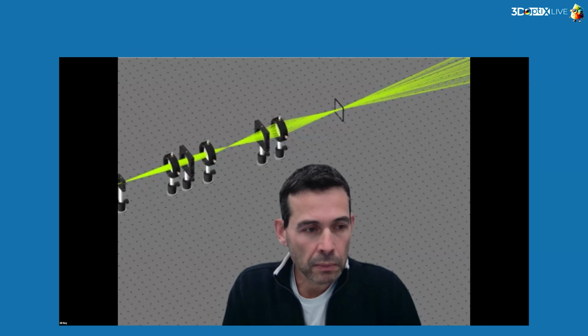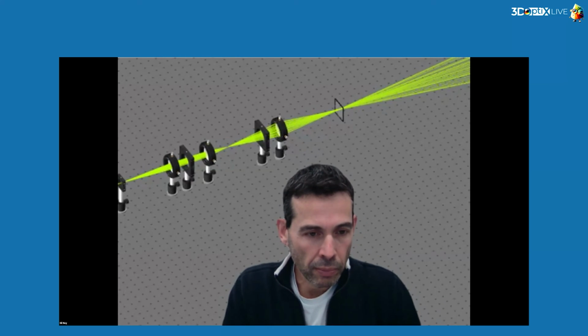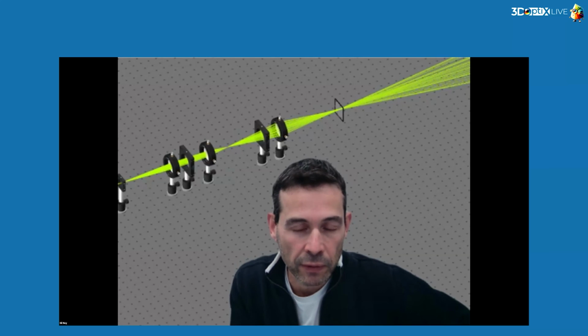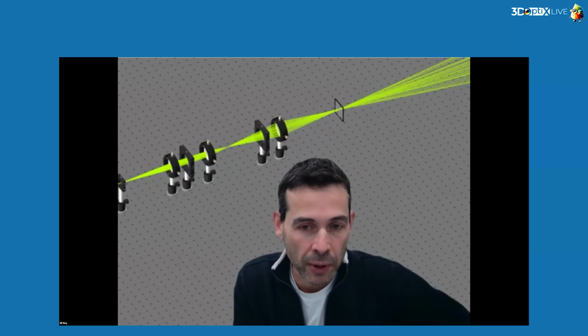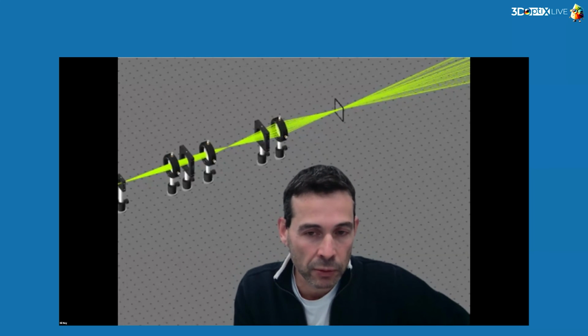And the good thing is you get instant feedback from this, so you can see every time you make a movement what's happening to the output of your light source. I would also like to add that we are going to add pretty soon, in several weeks, the ability to upload a ray file in the format of IES-25. Then you can get the LED's actual, measured ray file from the vendor, upload it to 3DOptix, and simulate that. That will be available in several weeks from today.